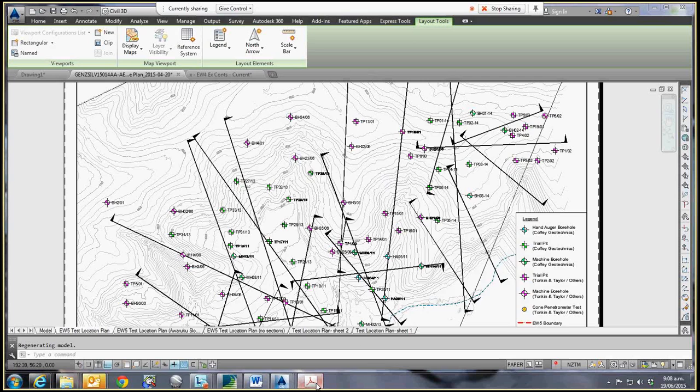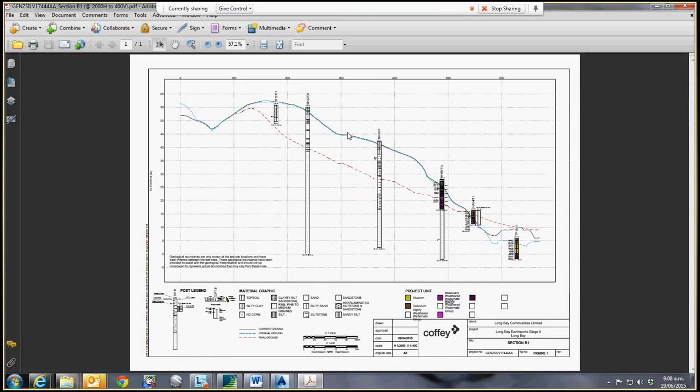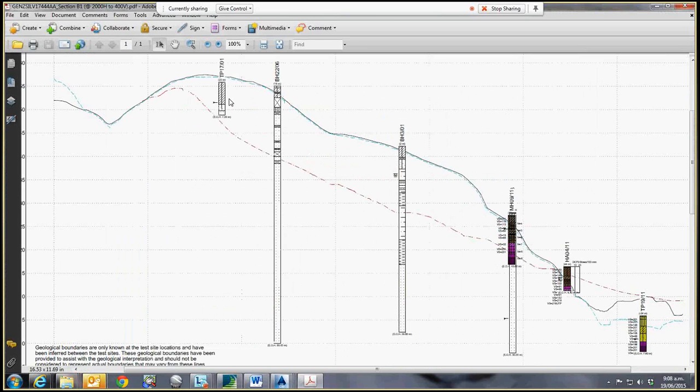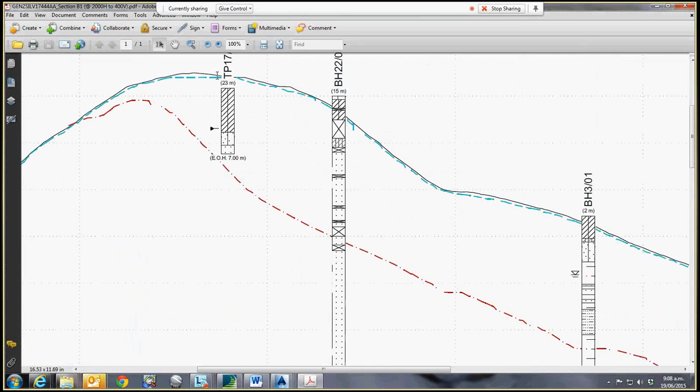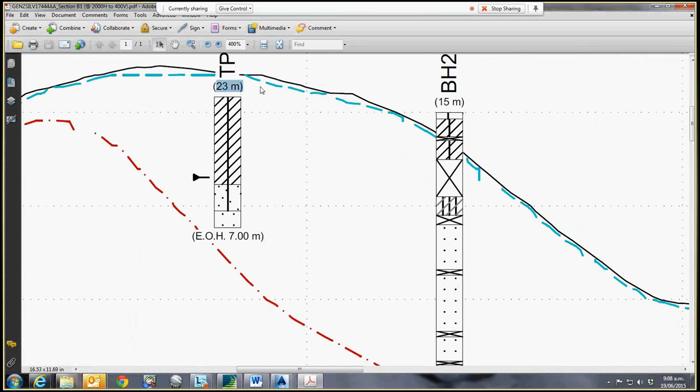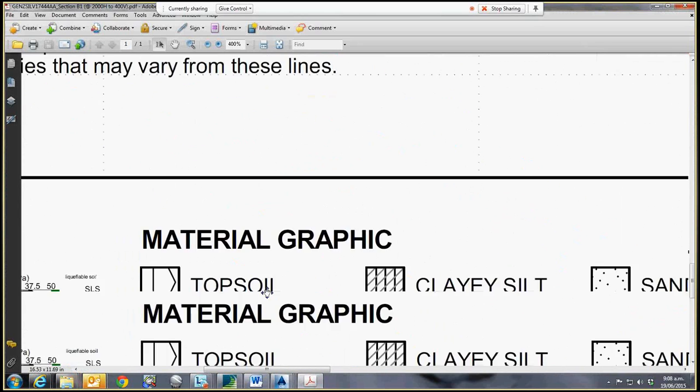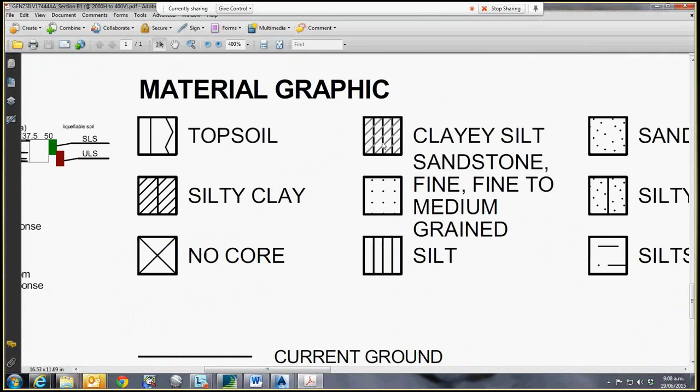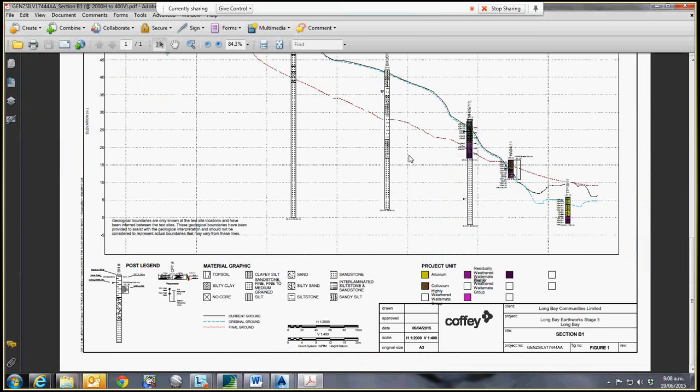And when you're done, you can get something like this. So this has all my boreholes at exactly the right elevation, exactly the right GPS coordinate system. It shows the offset, the depth of the hole, the little water symbol, the different material graphics. It puts a little legend down here for the different materials. And this is all done from gINT. I didn't have to put this in CAD at all.